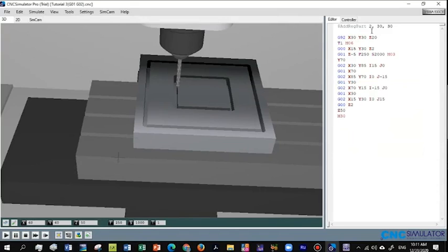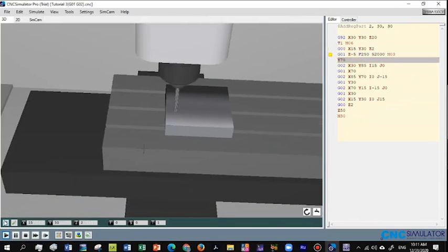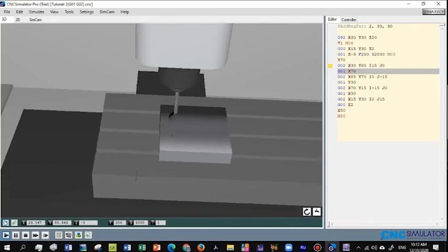So the same here, we use part number 2, define the place for the bar, then define the origin points here. Then what is the tool that we are going to use? For example, here tool number 1, also the same for milling. Then we have to define the mode code that we are going to use, since we are going to use circular profiling, which means there should be some rounding on the corners of the square, for example. If we run this one, you can see the dimension of the workpiece here is smaller.